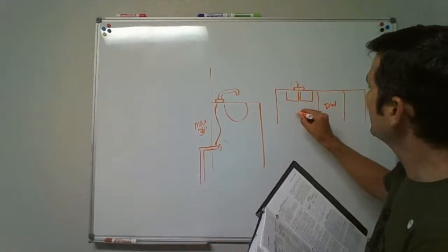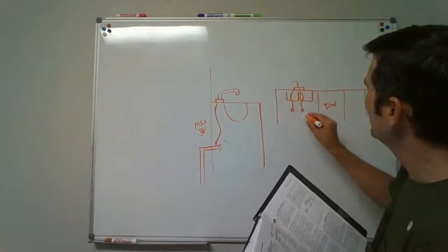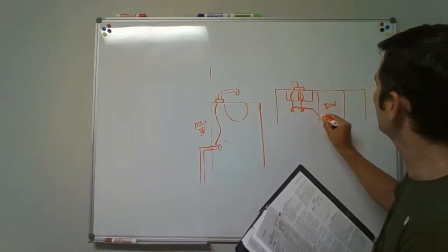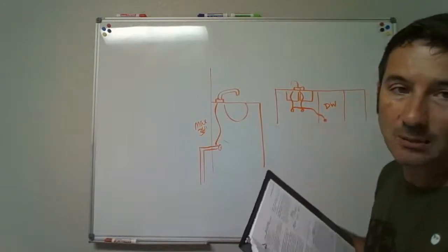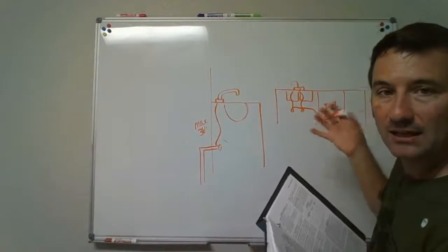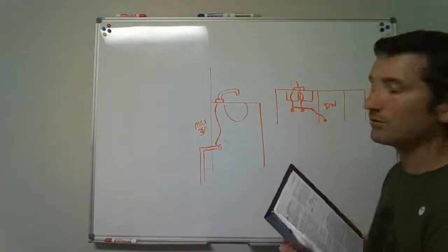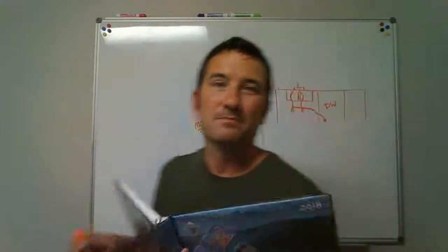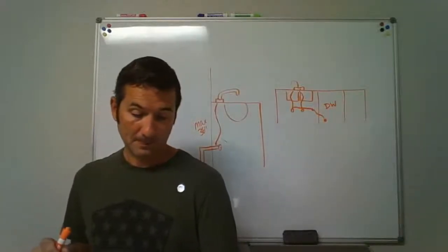A lot of times the water lines come out of here and feed up to those, and you've got another one that tees off of this and comes over and connects to the dishwasher. You've got to be able to pull the dishwasher and slide it out and in and hook it up. So we don't have a 36. That's going to be over 36 inches. A lot of times you'll get those supply lines about 5 feet long. Okay.